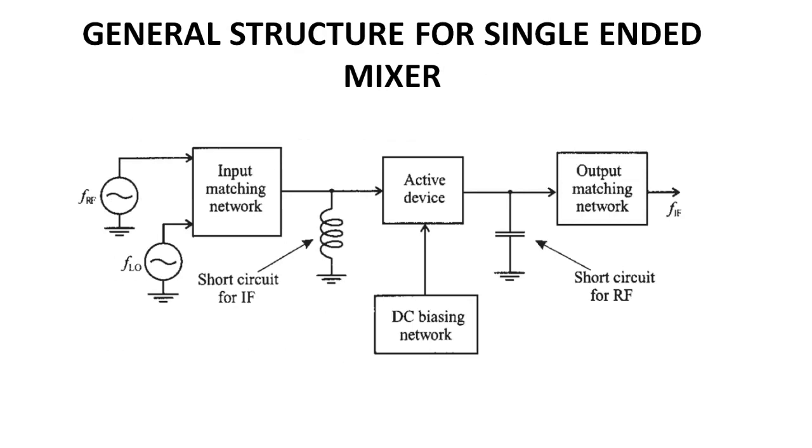The circuit design of RF mixer is shown in figure. The RF and local oscillator signals are supplied to the input of a properly biased transistor or diode. These are the active devices of a mixer. Matching networks are used at the input and output side of a mixer to avoid the differences in the frequencies. And to minimize the interference at the output side of the device, it is important to short circuit the input to IF and conversely short circuit the output to RF.